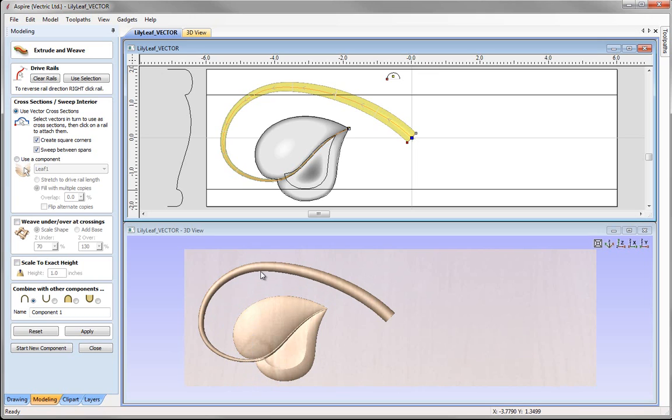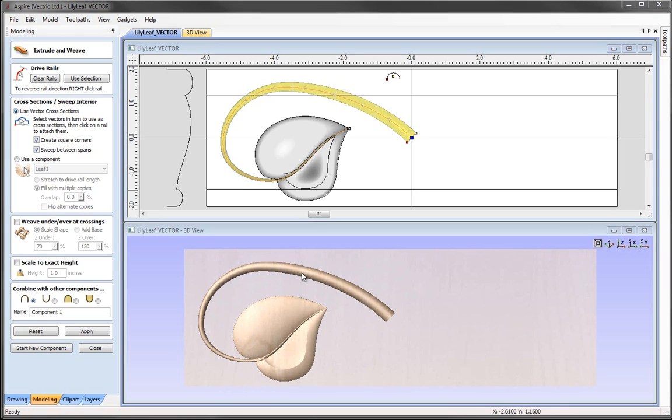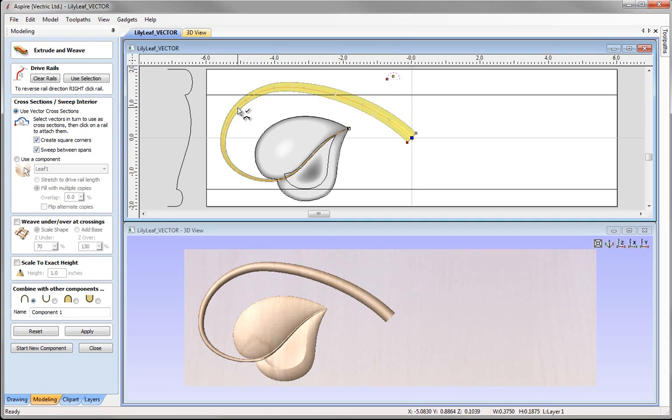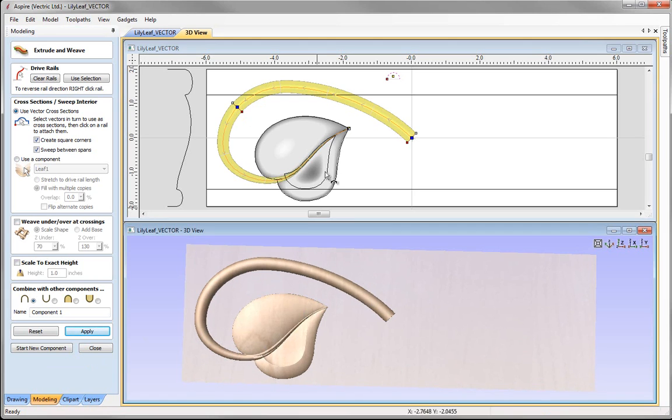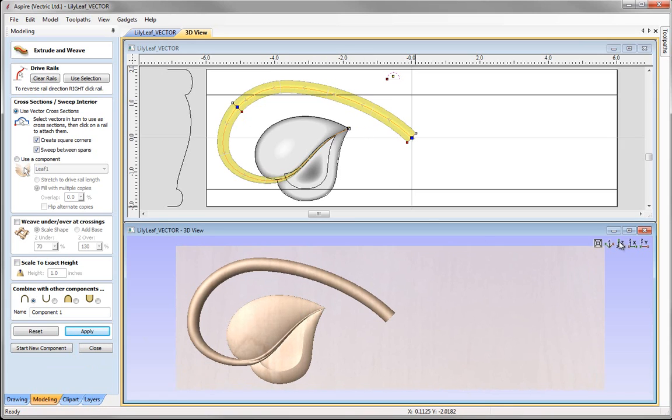Another thing that I'd like to alter is the cross sections, as I feel it's coming in too thin too quickly. So in order to maintain the shape of this cross section here, I'm going to insert that again but at a different point. I'm going to select the larger cross section and put that in position here, and then apply that. We can see that shape's being maintained a bit longer, and then it gradually gets smaller into that small cross section at the end there.